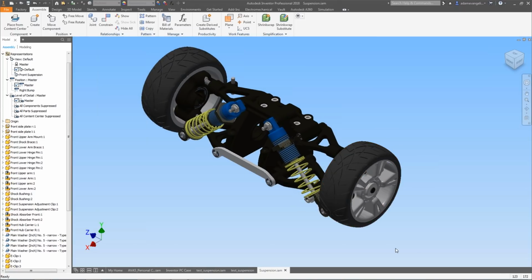I know you're also really curious about these two numbers down here, right? So you have a 123 and you have a 173 in the corner down there. The number on the left represents the number of unique files open in your assembly right now, and the number on the right represents the number of instances of those unique files in your assembly. So that number will typically be larger than the other one. I think it always should be. At best it should be equal, right?